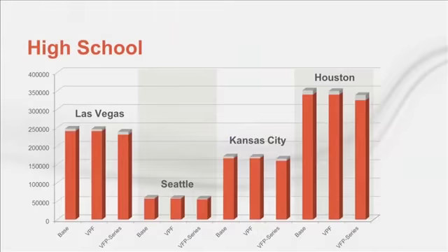For the high school, we used Chiller Plant Analyzer to examine two different system alternatives. With air-cooled chillers, input was simpler and took 40 minutes total for all 4 locations. The first alternative was to change from primary-secondary to variable primary flow. This reduces the pump energy a little, but a bigger factor is that this system's installed cost is reduced since we got rid of the bank of primary pumps.